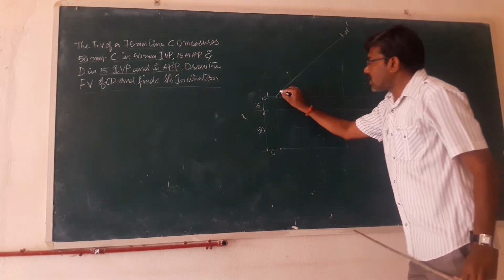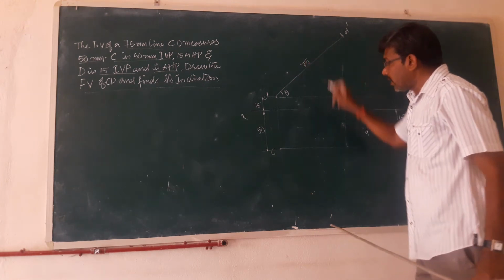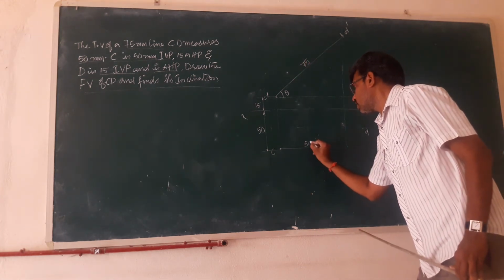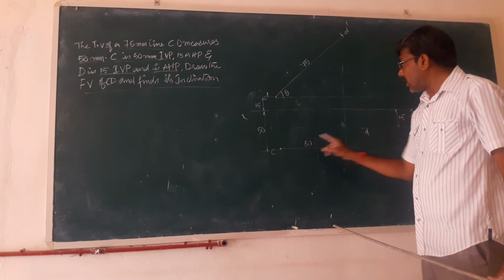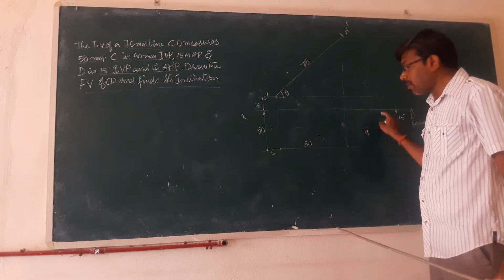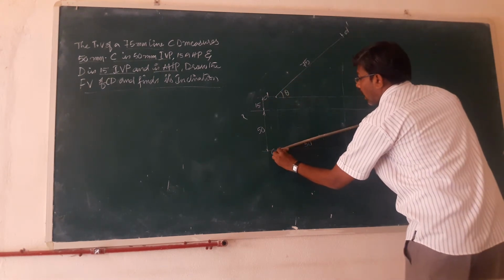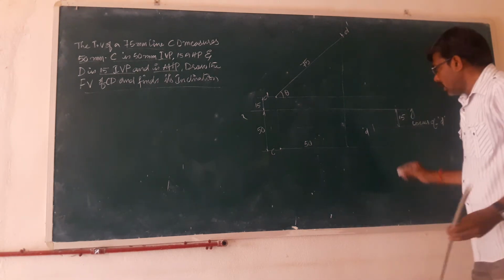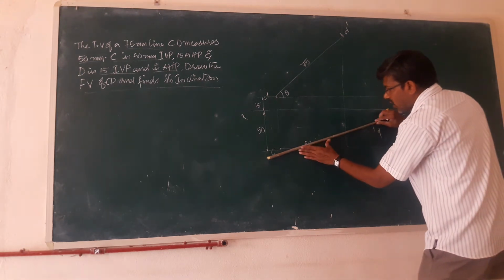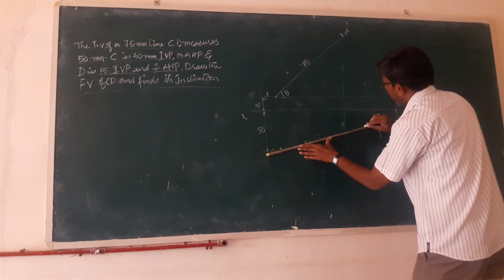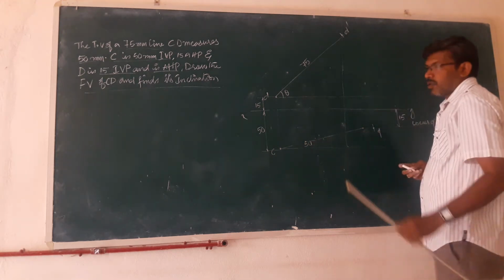Okay, when the line is inclined to the horizontal plane with some degrees with 75 as a radius, it becomes 50 in the top view. It becomes 50 in the top view. And where does the D dash is located? D is located 15 mm here. So simply by taking the length, the same 75, I locate this point and I draw it. So now I got this point D here. So this is the initial position of the line. Initial position of the line.